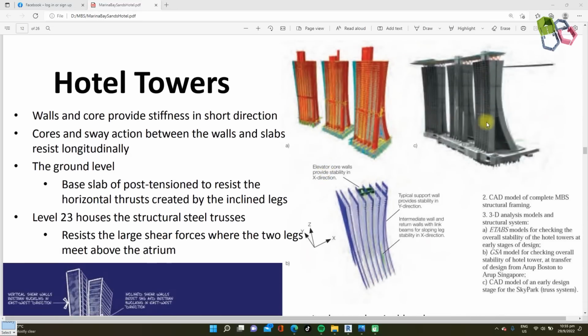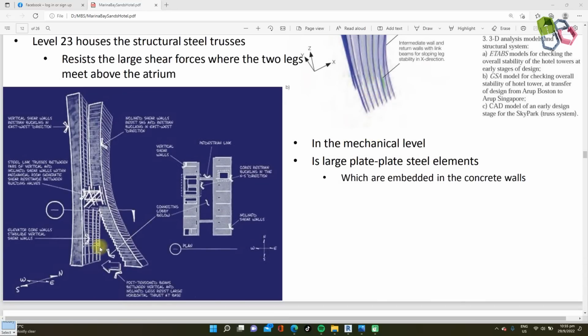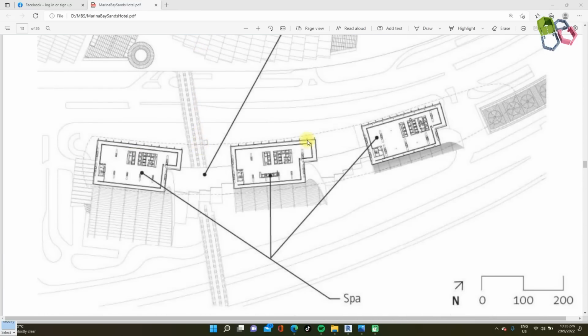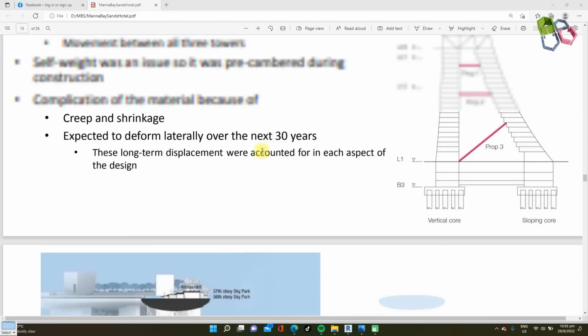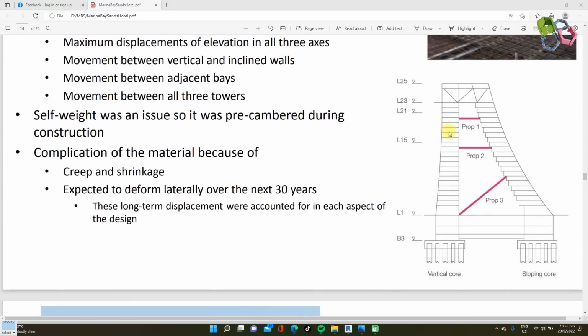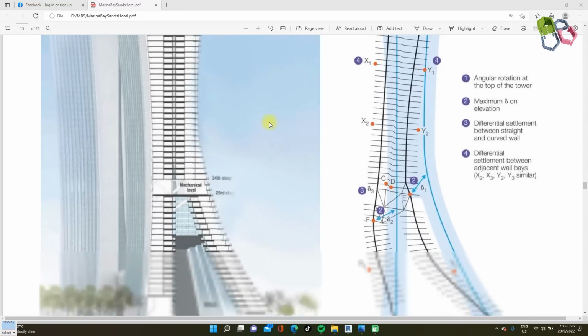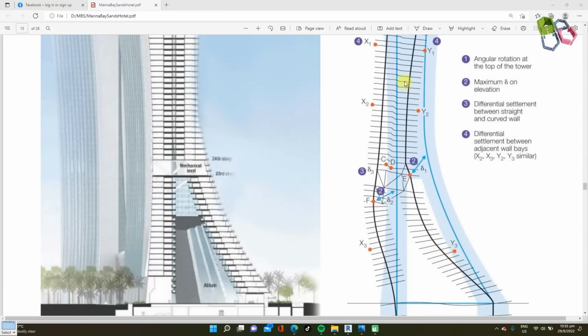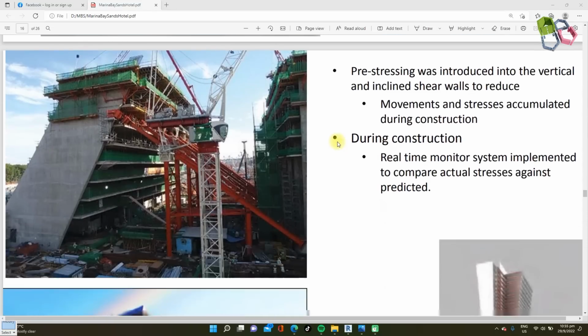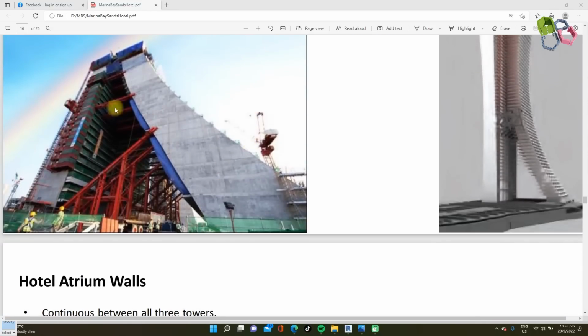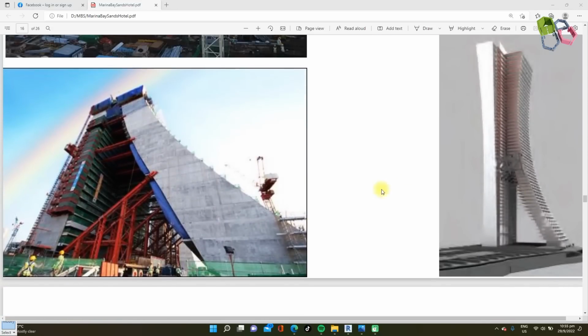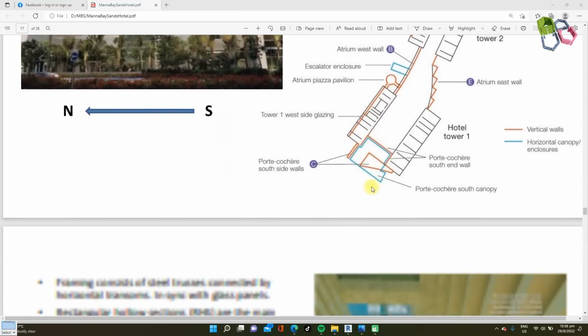These are structural cup shaped slender walls, and some construction diagram. Level 57 floor plan. This will be structural supporting members. I will create this slender wall. And this slender wall structural member I will create in an external family. After the family is created, log back into the Revit project and proceed with the model creation.